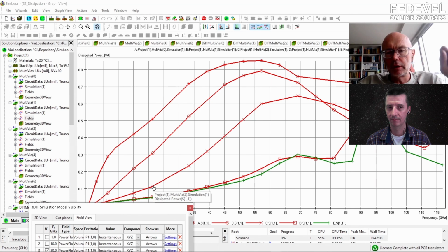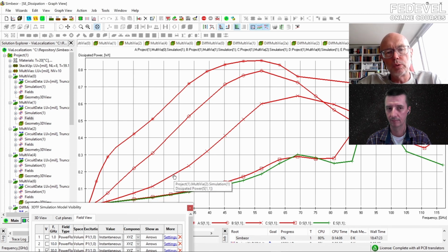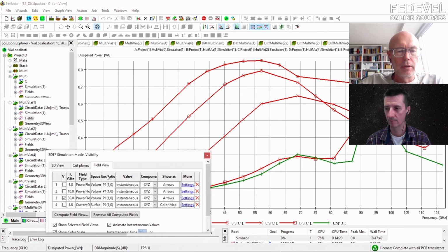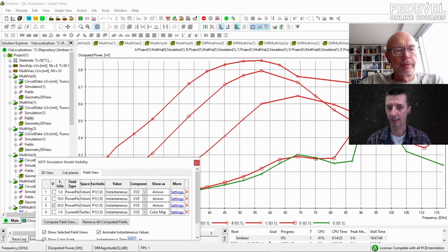It's always about the signal and how many stitching vias are nearby. So essentially you are gauging the energy. And we can take a look at what difference two vias make. You can see that the curve is growing much. You can get 30 gigahertz out of two vias, and then 4 and 6 are pretty much identical. You can get up to 50 gigahertz bandwidth. So for very high speed, at least 4 stitching vias are required.